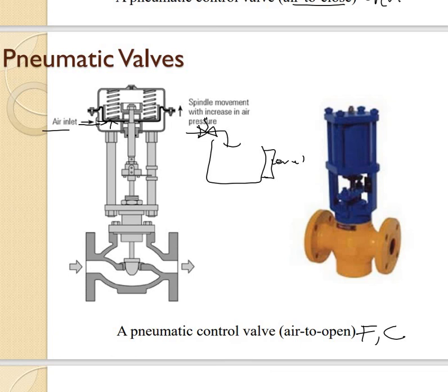If an emergency occurs and we use this fail close valve here, it will directly close the valve, so there is no fluid feed inside the tank system, so the level will be maintained.